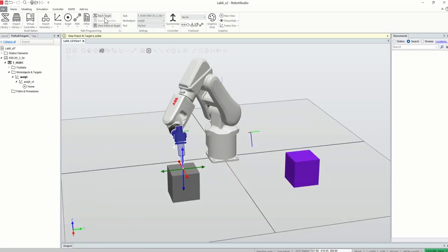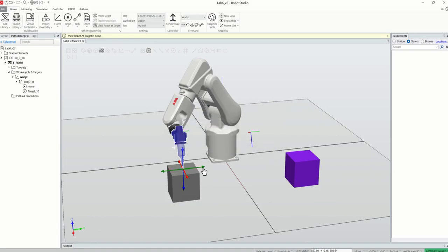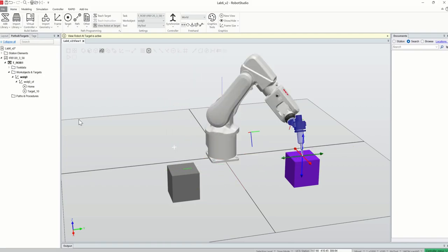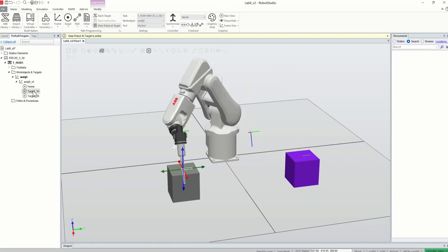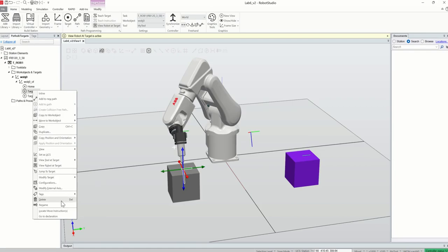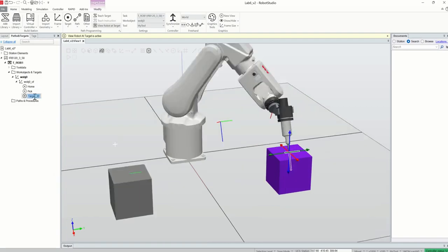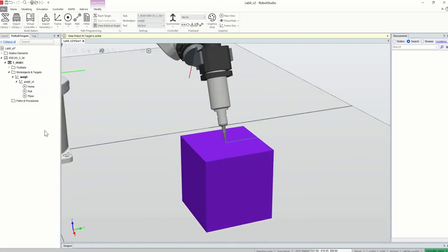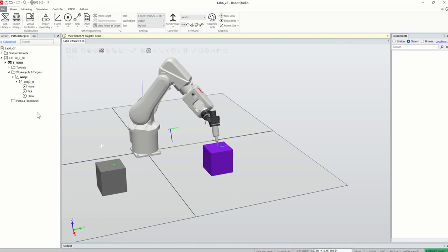Then I can create a very simple teach target. Yes. And I'm going to do it this way, and it is snapped by itself. When you are going closer to the center, I'm creating another target. So that's how I got home, target 10 and target 20. And as I mentioned in the question, you would need to make this one as pick and that one as place. Once you're creating that place, I need two more targets, like two more approaching targets.